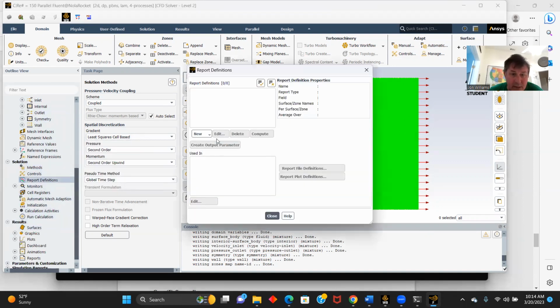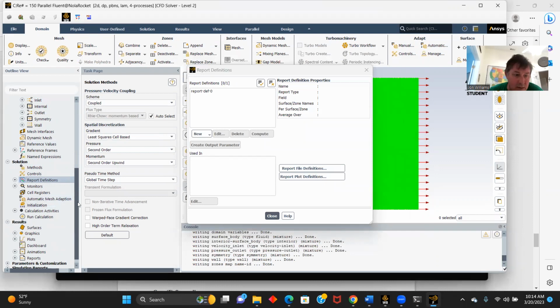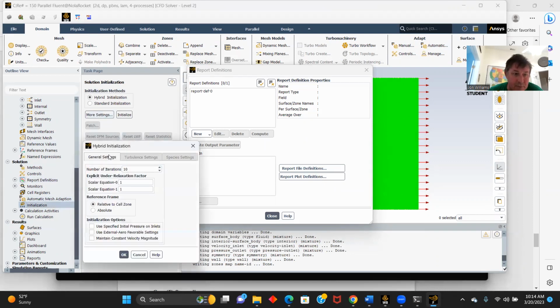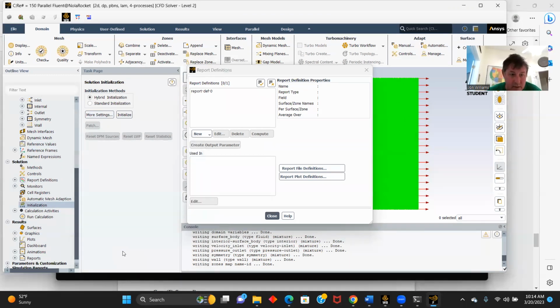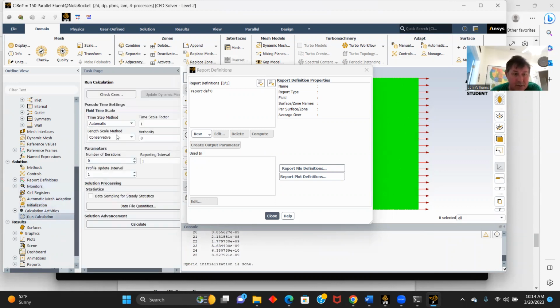Report definitions. Yes, we want to report our drag forces again on our wall into console. Okay, and we will do initialization. 25 iterations here. Okay, initialize. Okay, and then we will run calculations.